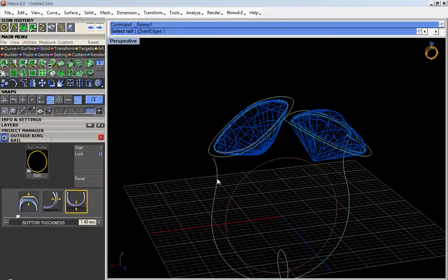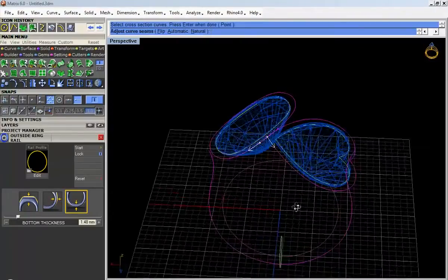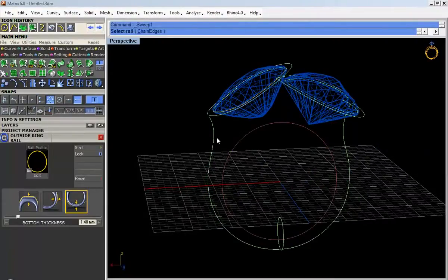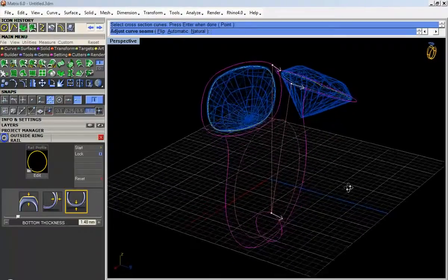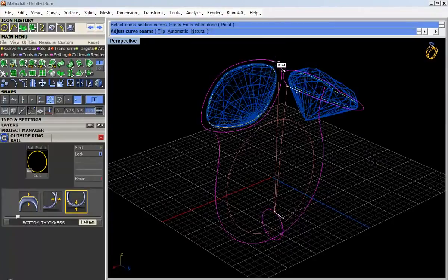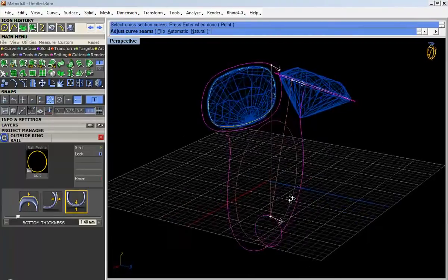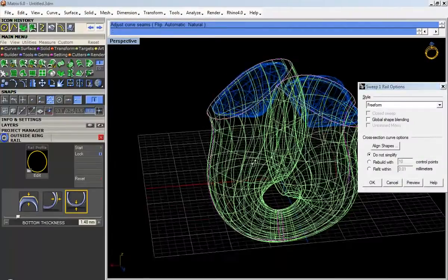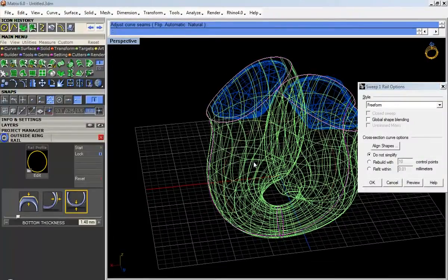Surface, sweep one, select here, and then you press enter. Alright, I missed the down one, select, select, select, and select. Alright, so this is how it's gonna come. It's gonna come in this way, facing this direction. When it comes over here, this faces this direction, and it goes over here, it faces this direction, which is perfectly alright. You're gonna learn them more when you try to do sweep 1 and sweep 2. When you go with the sweep 1 and sweep 2, you understand them more.